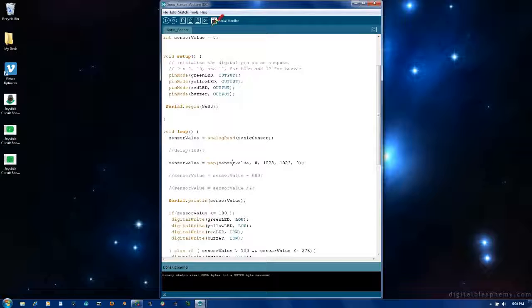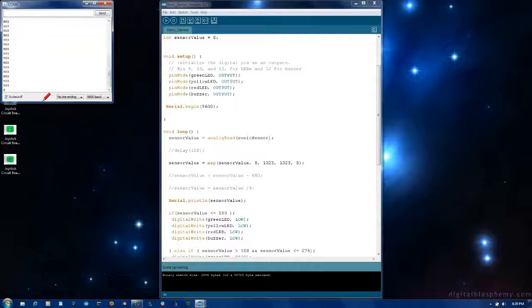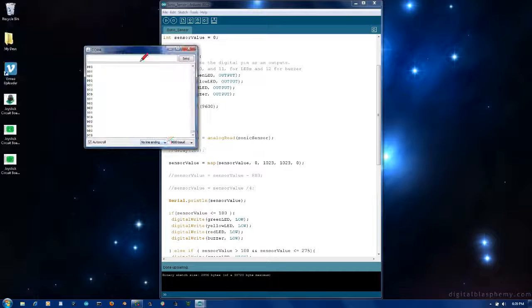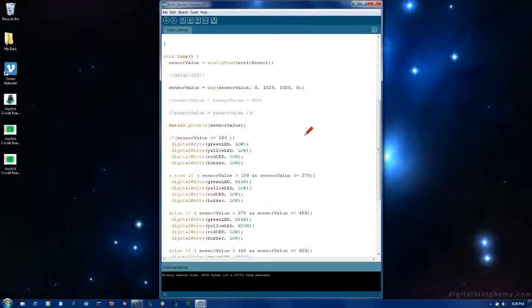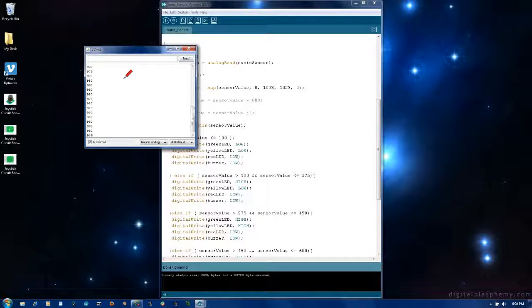And of course, everything comes on, and when we look at our serial monitor, we're in the 900s, so we're reversed. We don't see 111 anymore. But now we have a problem. This sensor detects objects up to 25 feet away. Well, what is 25 feet away? Well, 25 feet away is 0. And now I have this pointed at my ceiling, and I'm getting 980.